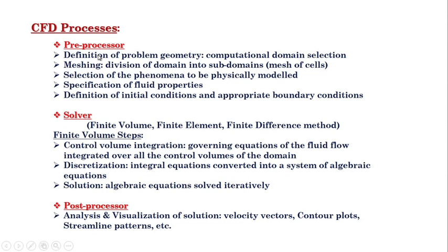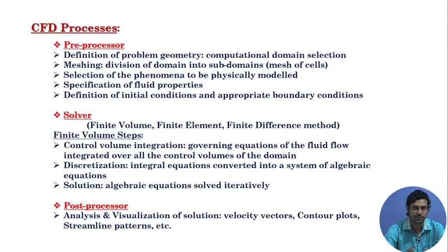In the preprocessor, you first define the problem geometry, meaning computational domain selection. Next you divide the whole domain into subdomains, meaning meshing. Then you select the phenomena to be chemically or physically modeled. Then you specify the fluids involved in the problem, and you have to define the initial conditions, meaning pressure and velocity at initial time, and very carefully define the boundary conditions, meaning pressure and velocity at boundaries, that is wall, inlet, outlet.